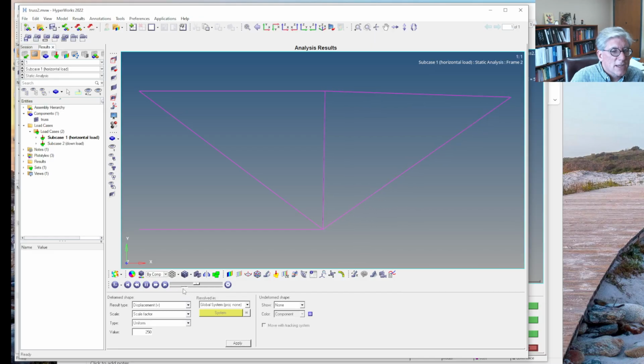If you slide this bottom slider down, it changes the playback speed, and that's useful. No, I think this is right. You can also change this button here, and it'll do a couple of different modes. This one oscillates between positive and negative, like we're doing a vibration. But for us, the good one is transient animation mode.